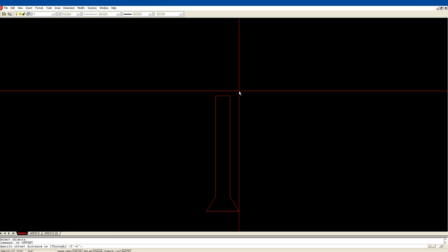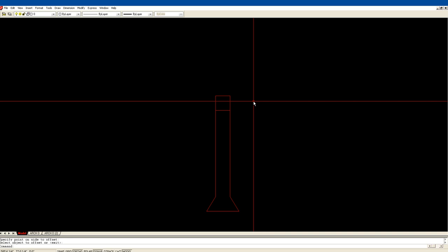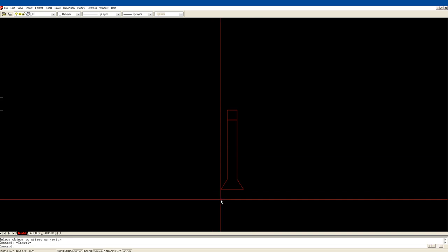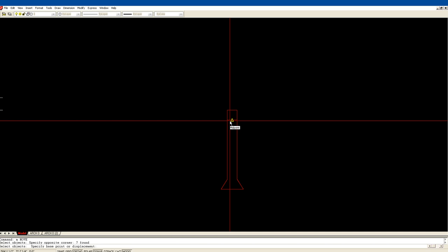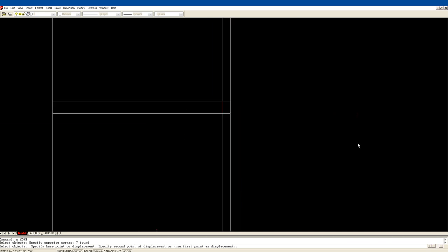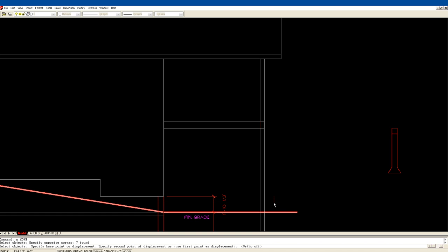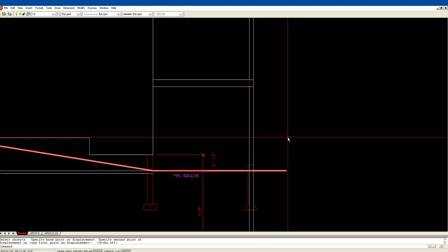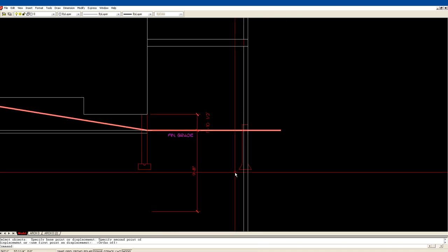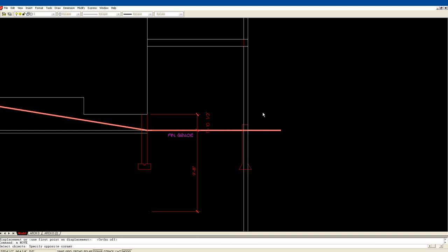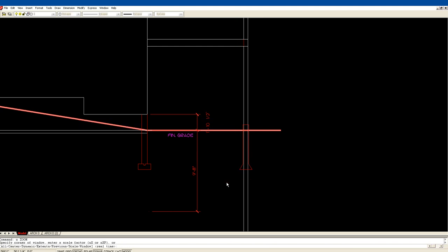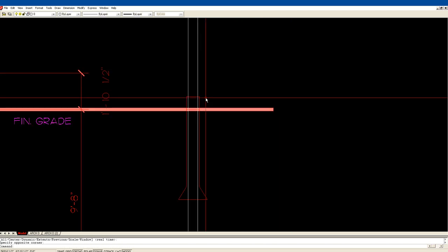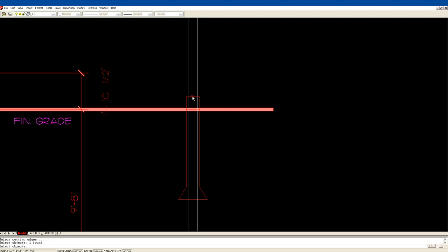And then I'm going to offset 8 inches. I'm going to have 8 inches of this concrete showing. And I'm going to move this from where? Well, let's go right there, and turn F8 off. And I'm going to put it right there. Now we need to center this on the post, so I'm just going to move it in a straight line, 1 inch over. Okay, so that's an 8-inch round concrete on a 6-inch post.